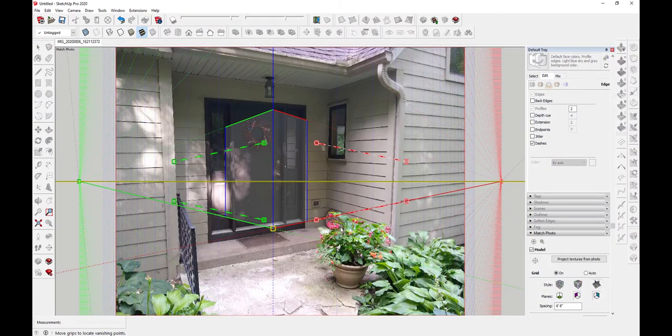Most of the time when people see this, it's kind of like, what's going on here? I broke the machine or something, but it's not that hard to determine. You're going to get these bars here, and these bars are basically showing the perspective vanishing point in the green axis. This one's here showing perspective vanishing points in the red axis, and of course the blue strip and down. And this yellow box is the origin. That's where we drew our door, in the origin.